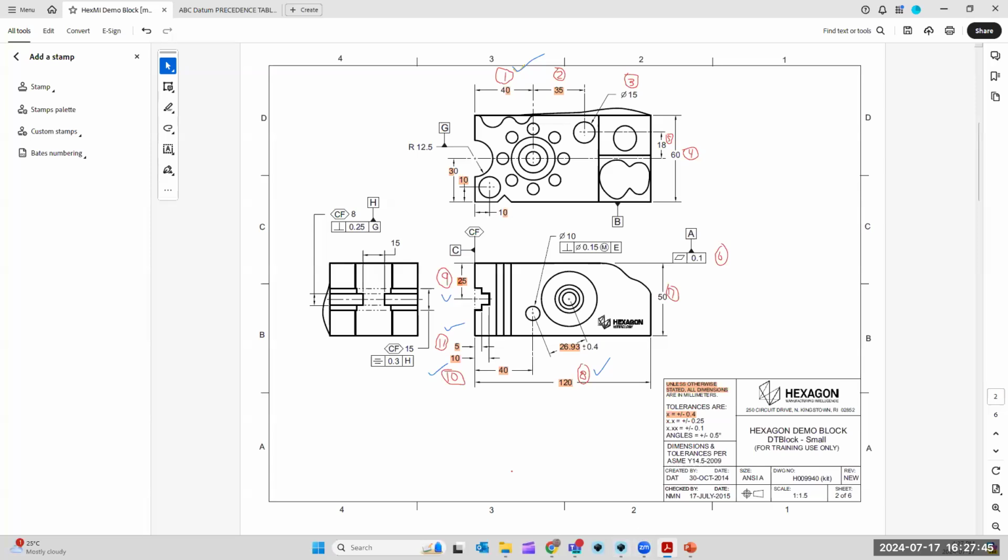To do that, what I'm going to do is identify the tolerance of my 40 millimeter. That's the nominal dimension, or the nominal position, of that feature, right? 40 millimeters from the edge. Well, what's my tolerance? We talked about this earlier. Plus or minus 0.4 millimeters.